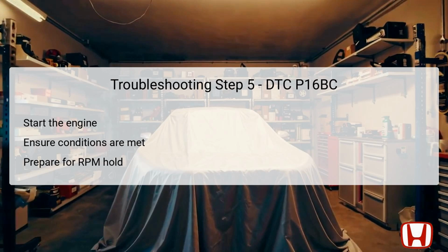Holding the engine speed at 2,000 RPM for 1 minute while maintaining these conditions provides useful diagnostics. This controlled environment is critical for evaluating the alternator's ability to supply sufficient voltage when under load, which directly relates to the health of the vehicle's electrical system.